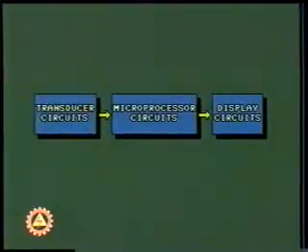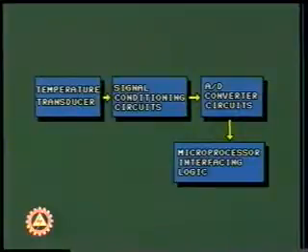Consider a microprocessor-based temperature controller. At global level, we look at a black box which is called the microprocessor. We open this box, we look at the transducer, microprocessor and display. When we open up the transducer box, we look at the temperature transducer, its signal conditioning circuitry, interfacing to an AD converter, interfacing of AD converter to the microprocessor.